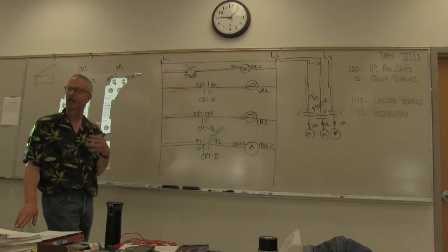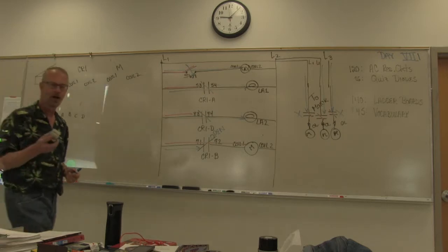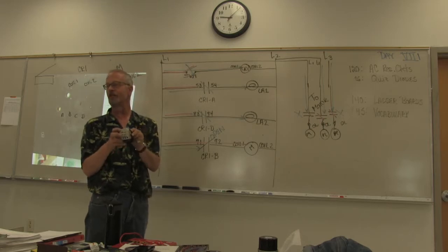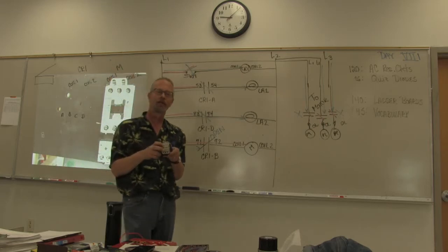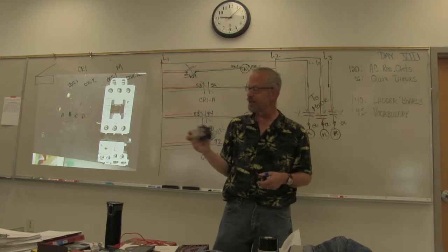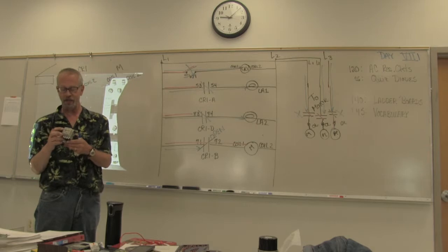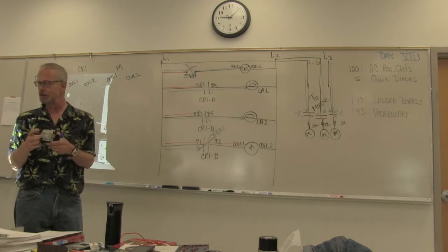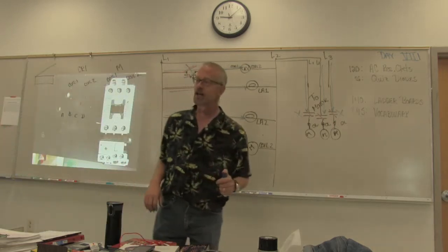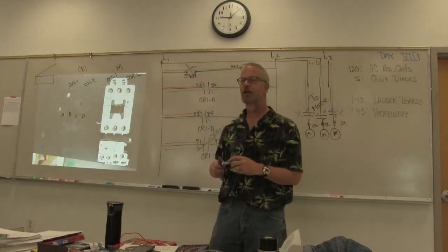So you always have to look at shelf state. Shelf state means, what is it right now? If I were to take an ohm meter right now and ohm out the normally open contacts, I would see an infinite amount of resistance there, hopefully. And if I ohmed out the normally closed contacts, since this is a normal condition and it's closed, I should see roughly 0 ohms. When I switch it, which I can simulate by pushing that button, then everything should convert over to its non-shelf state or active state, and the closed will become open and the opens will become closed.